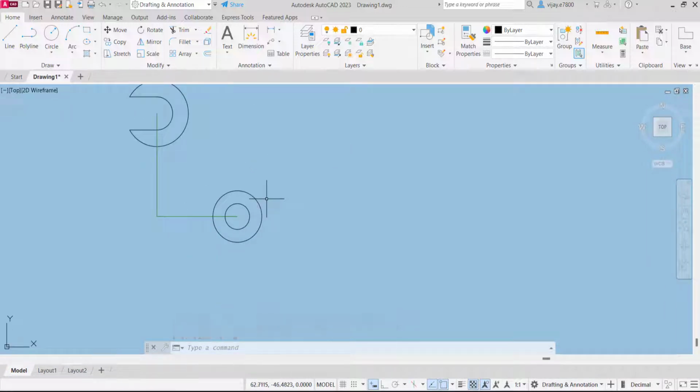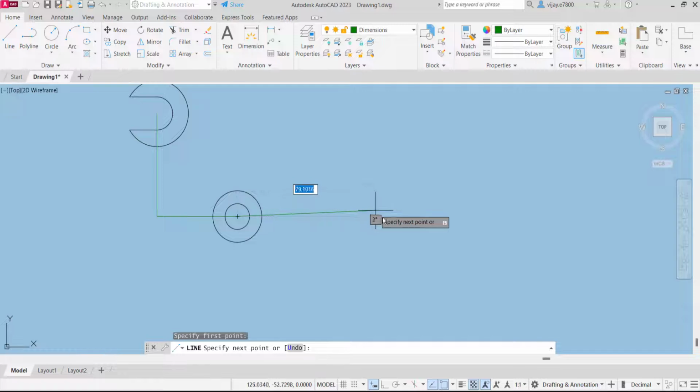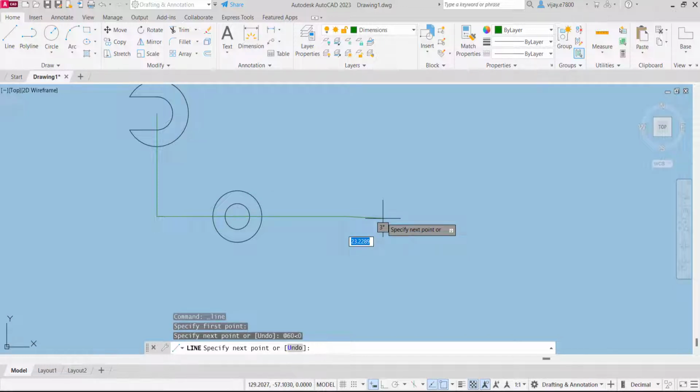Now after that, the next thing that we need to do is we will move 60 units and then 39 units. So 60 units on the right side, select a line. Now move to the dimension layer itself, select a line, now go 60 units, so at the rate 60, then less than 0 at an angle of 0-degree and then press enter.